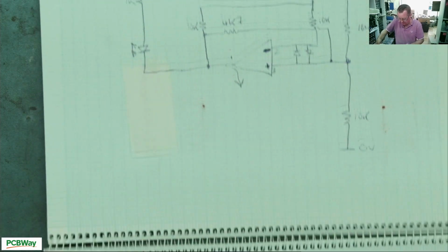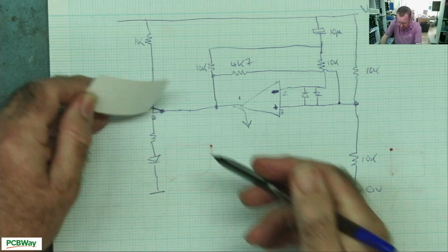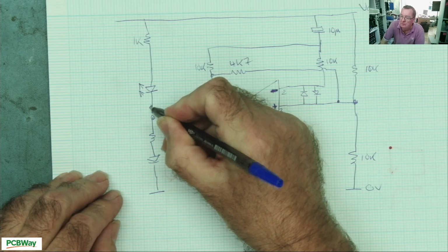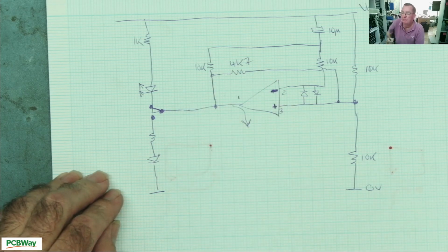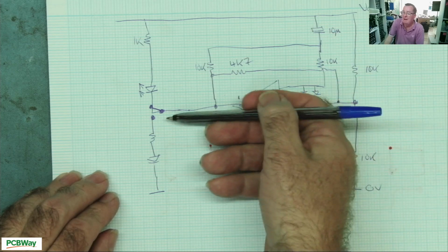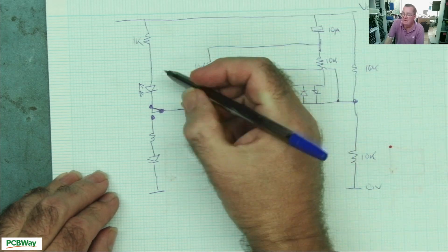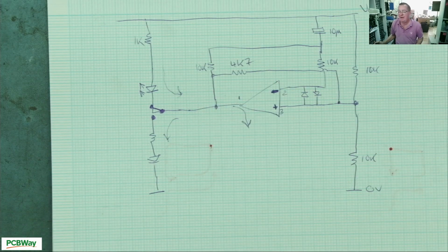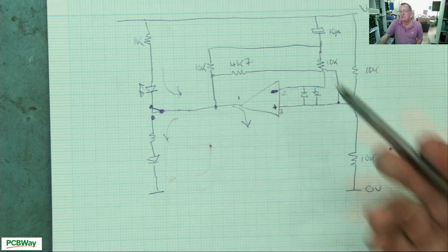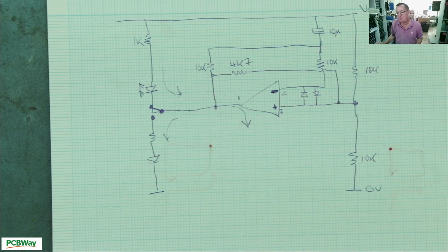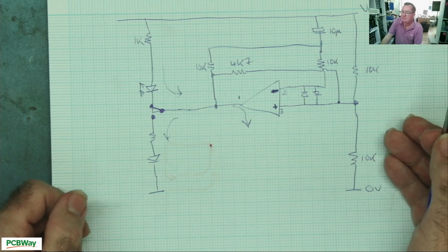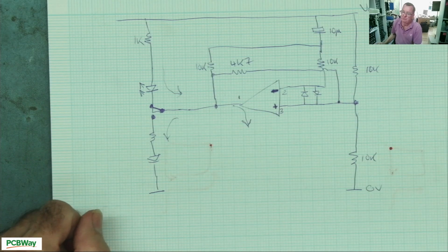So I thought, well, if that's the only difference, if we put a switch here, single pole, dual throw, the output can either be set to sink current or to source current. Yeah? And you can switch the switch in the up position to test comparators and in the down position test op amps, and therefore we don't need 4 of these for testing op amps and 4 of these for testing comparators. We just need 4 of them and switch the output.